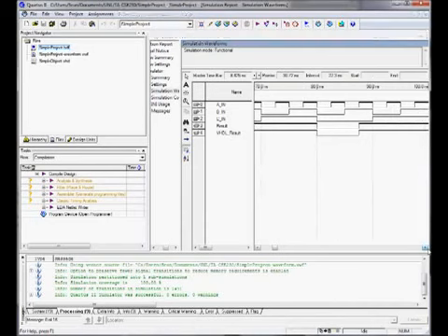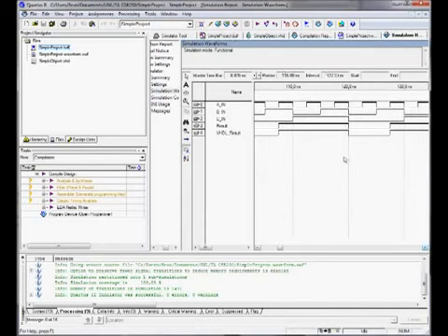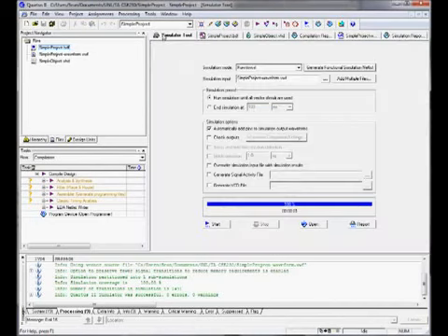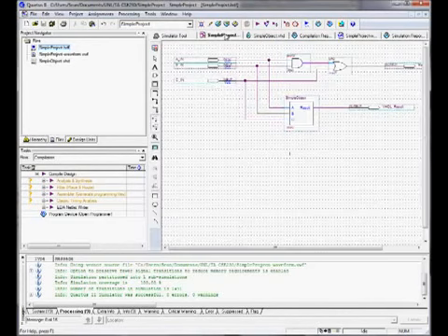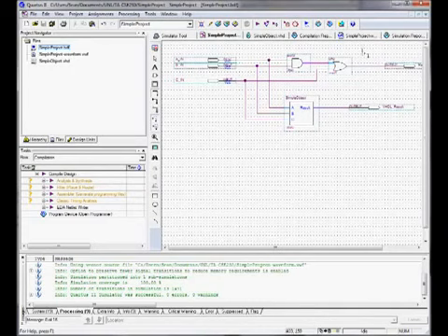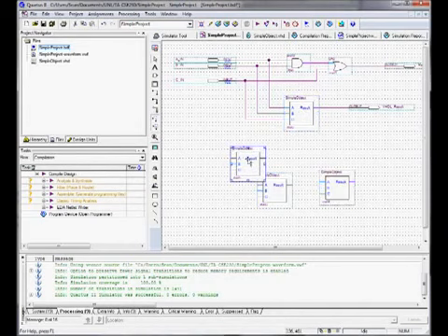So we're successful. So that's two ways of looking at a project, essentially. What you have here is a schematic capture version, which allows you to draw things in by hand, which can be very handy for connecting up objects that you've designed internally. For instance, if I have a bunch of these little VHDL objects, I want to wire them up, I can just copy and paste them all over my diagram. And all I have to do afterwards is just wire up where I want them to go and what I want them to do.